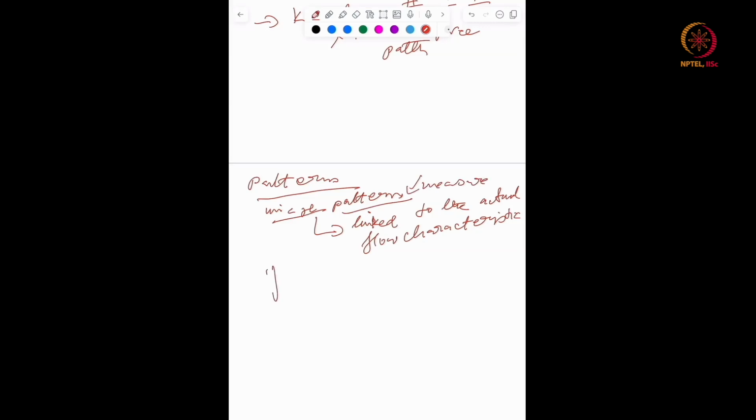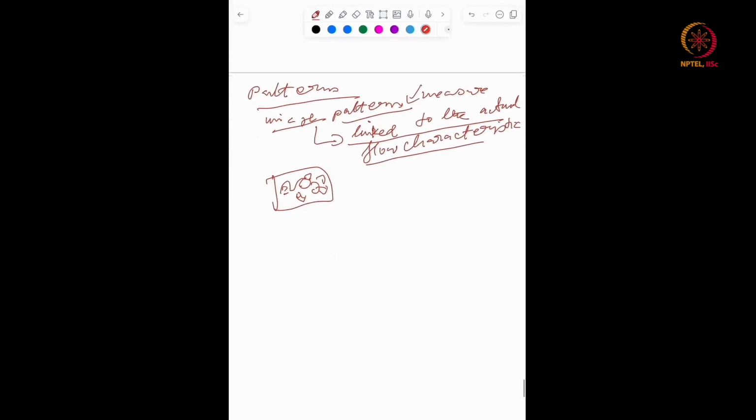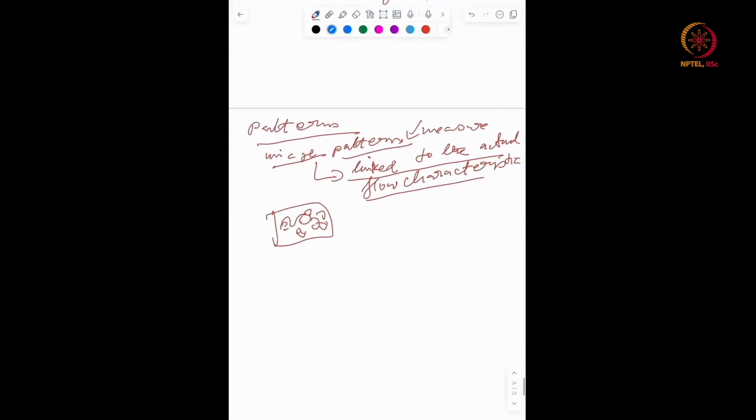Okay? So you can see, for example, you get all these kinds of flow velocities, you can get all kinds of vector fields around it. How is it linked to the actual flow characteristics? There are ways, for example, you can take an instantaneous position of a fluid particle or marker provided by a still camera with a short exposure time. So you can determine the instantaneous position